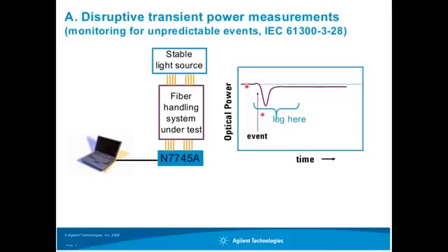in post-processing the computer detects it has moved beyond a certain threshold, maybe half a dB, then it will record that data, potentially with pre-trigger and post-trigger data, and store that, can label it as an event, and that can be characterized afterwards. When might that happen? Could be that it's tested while someone is changing the configuration of other fibers in the system. It might also be a test for what goes on during temperature cycling of a link, and especially the connectors.